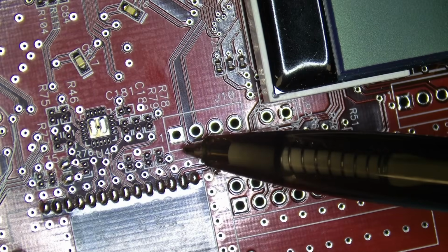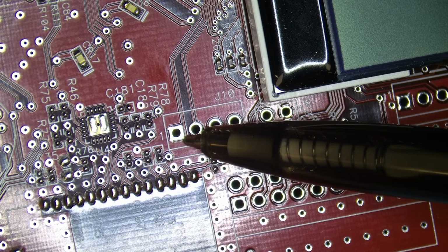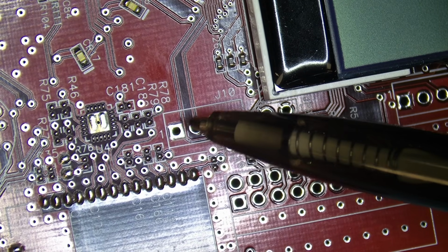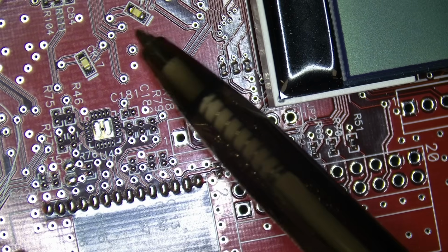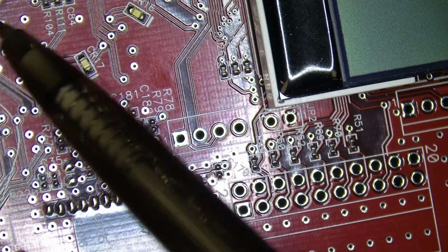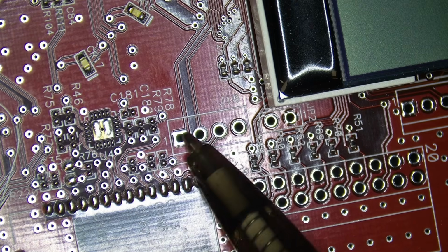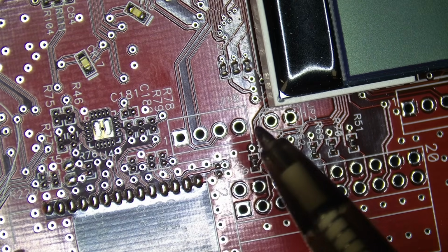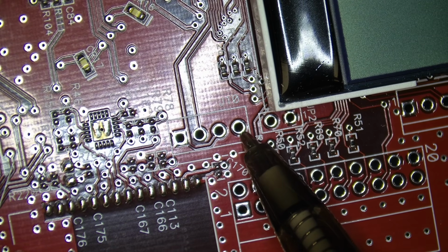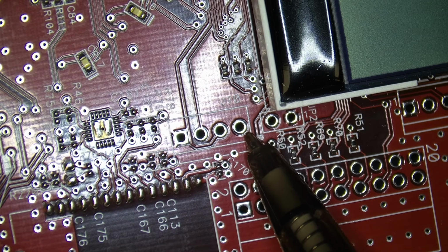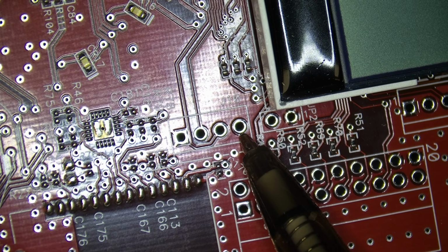And look at this guy. That guy right there really looks like that one's ground. It's got a little connection right here that goes to all this plane right here, all this up here, all this right here. So that is almost definitely ground. And then this one over here is VCC, but it doesn't really look like it's connected to anything. But guess what? I already said that for UART, you don't necessarily need VCC.